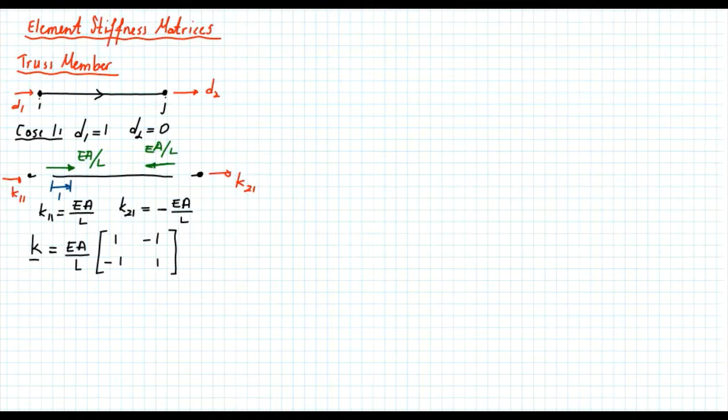The other element type that we see is where we use the modified equation. So I will call it beam member with a hinge. So here the hinge represents that at one end, it could be the start node or end node, we have a free rotation, free to rotate condition. Now, case 1, let's say that hinge is at the end node.